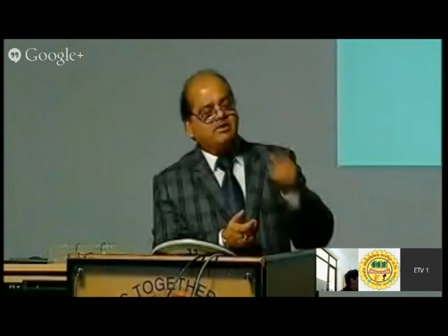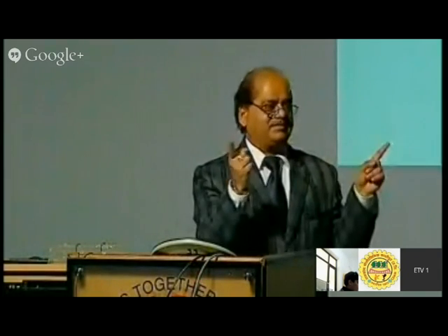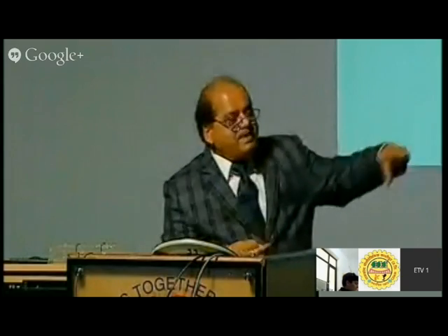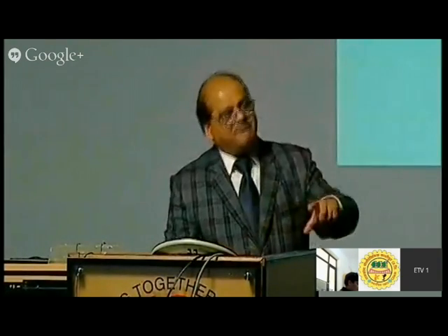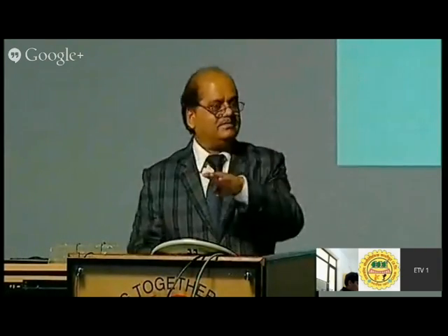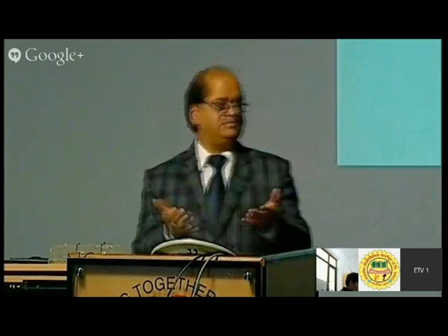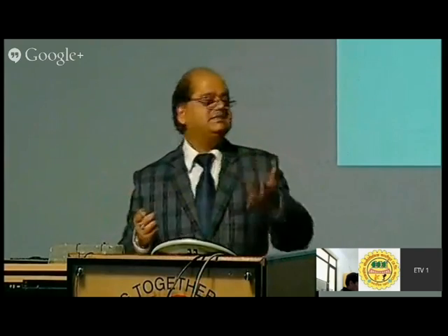I cannot send a number of currents on the same copper because they will generate sparks. But I can send a number of wavelengths on the same fiber because each wavelength will follow a different path. So the wavelength has to be different. That is a unique feature of optical fiber communication. So WDM is possible. It is similar to frequency division multiplexing.